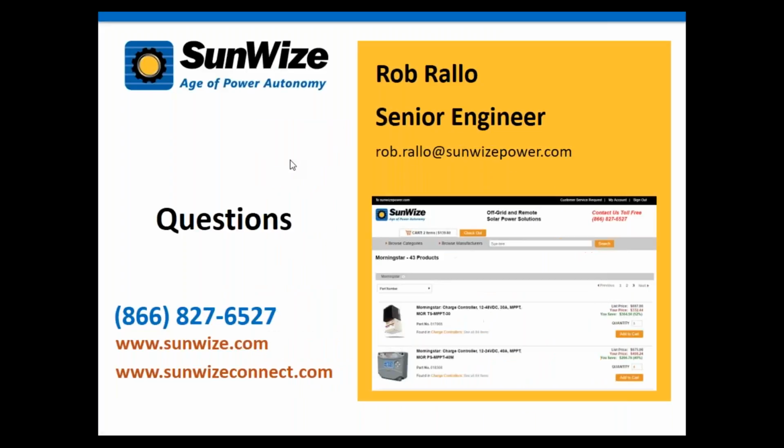If you're going to manually adjust the array tilt angle during the year, do you use latitude plus 15 degrees for the spring-fall position? Interesting question. Generally, I would use the latitude plus 15, because that's where you're going to leave it for winter anyway, and winter's always going to be worst case.